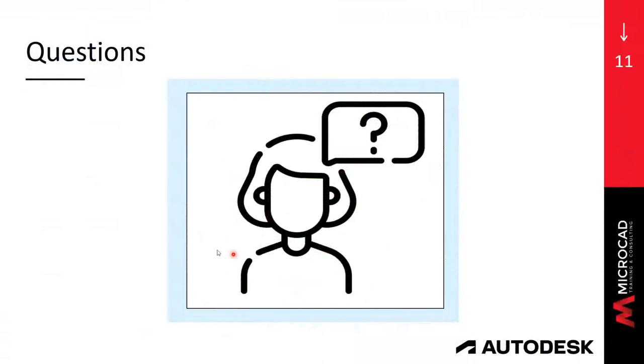Thank you. Next question is, the survey point and project base point should not be too far away from each other. What do you recommend in a situation when you acquire coordinates and the survey point moves too far? Well, Revit gets very unstable if anything is modeled too far out. I think it has a 10-mile radius from the internal origin.